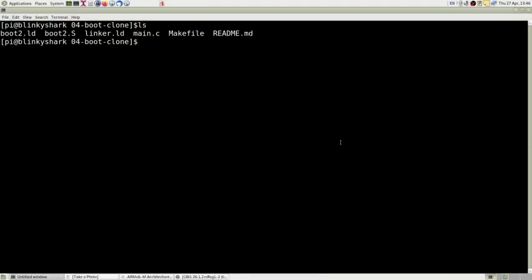Escaping the boot2 sector. You only get 252 bytes to play with in boot2. That's obviously going to be quite inadequate for most purposes, and we need to somehow break out of the boot2 sector into the main flash.